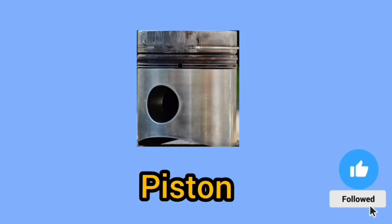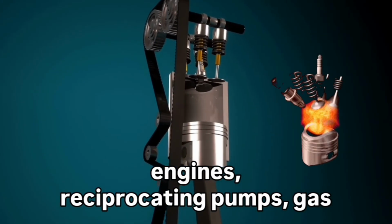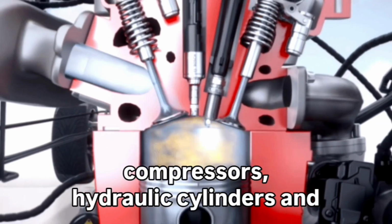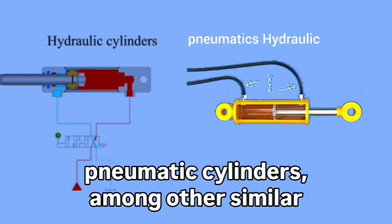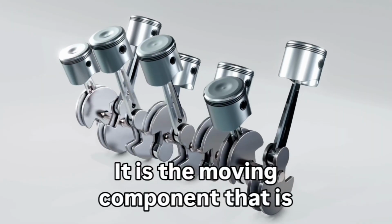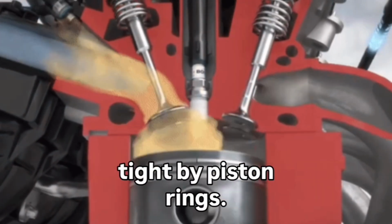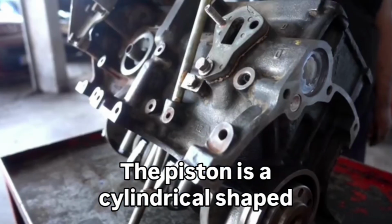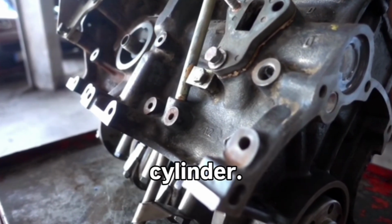Piston. A piston is a component of reciprocating engines, reciprocating pumps, gas compressors, hydraulic cylinders, and pneumatic cylinders, among other similar mechanisms. It is the moving component that is contained by a cylinder and is made gas-tight by piston rings. The piston is a cylindrical shaped component that fits perfectly inside the cylinder.